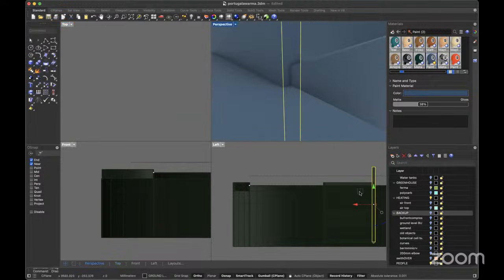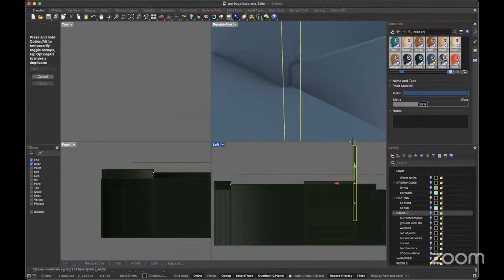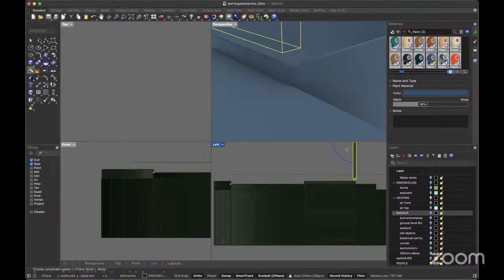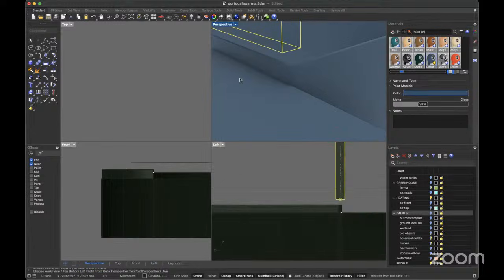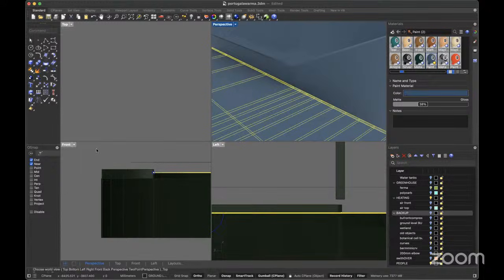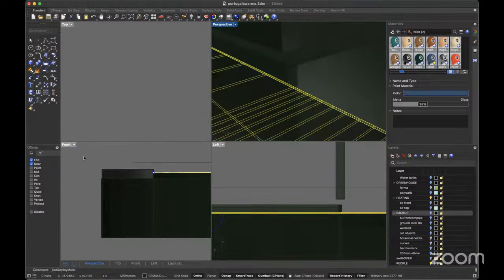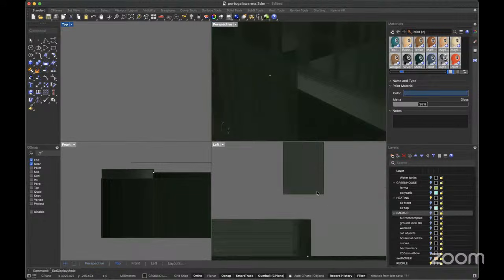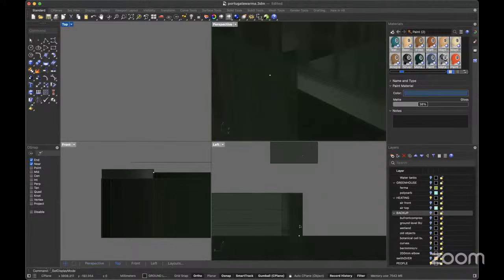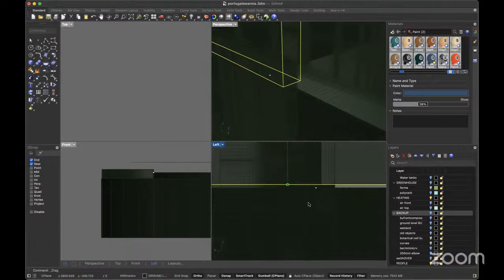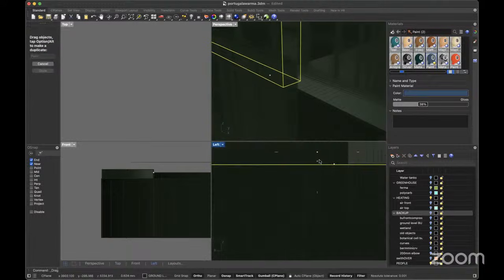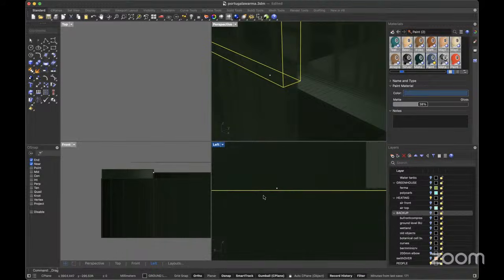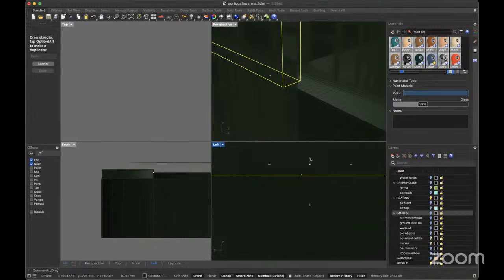Okay, and I obviously need to align it up. Where up? I need to put a point so I can see where up. Okay, then I can see that point. It's somewhere hidden there. Obviously, to see it, you need to go ghosted. And if you still can't see it, X-ray. There's the point, yeah? So just bring this down towards the point. Zoom in, down towards the point. Zoom in. And that's good enough. Up, zoom out.